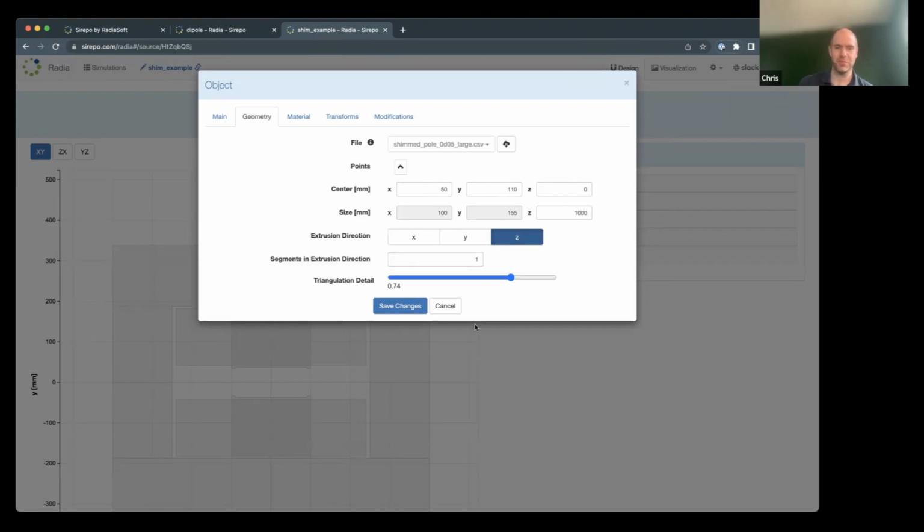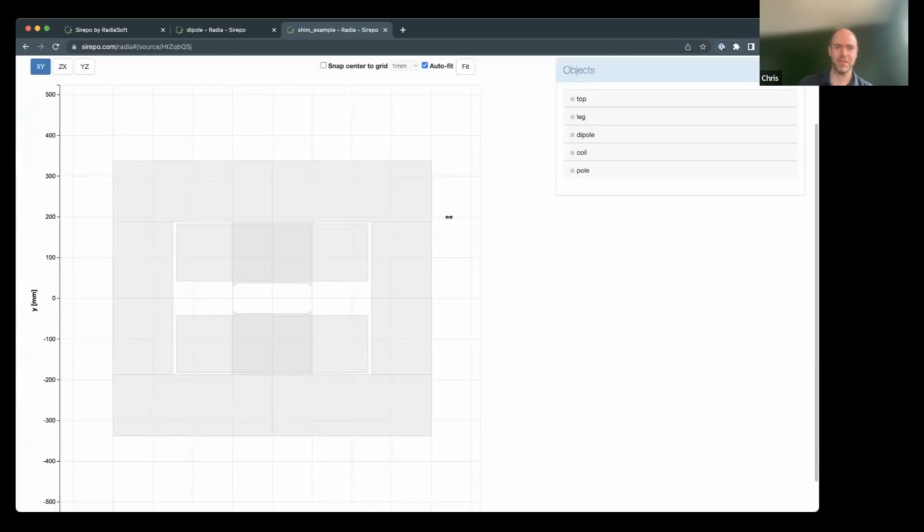Assuming that you've implemented the magnet design exactly as you envisioned, there is going to be a fair amount of dependence if you segmented it properly. For instance, around these corners here, you would probably want a lot finer segmentation as the field is changing direction rather rapidly. So if you only have a few segments here, you aren't going to fully capture that change.